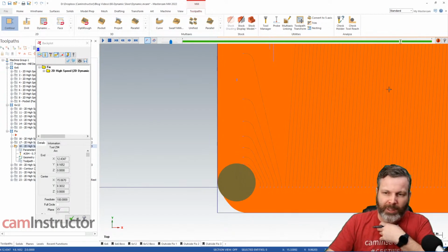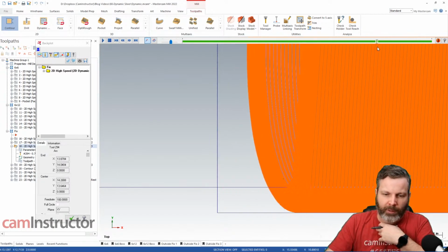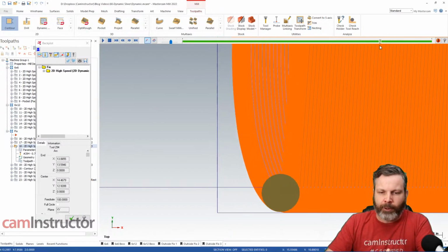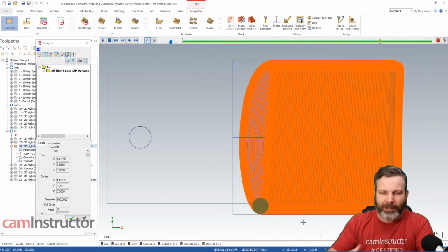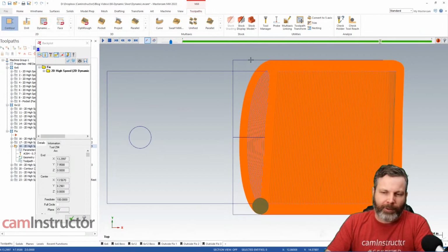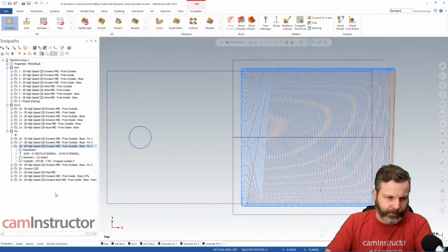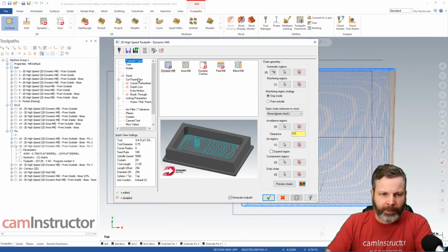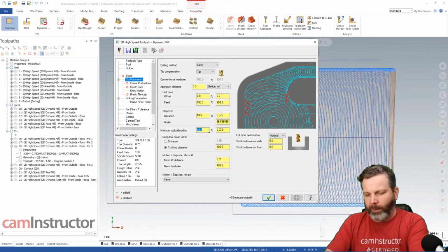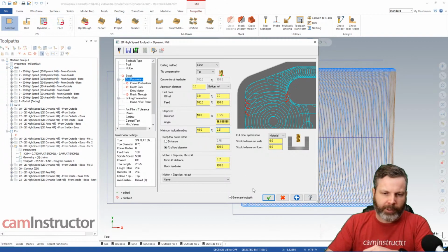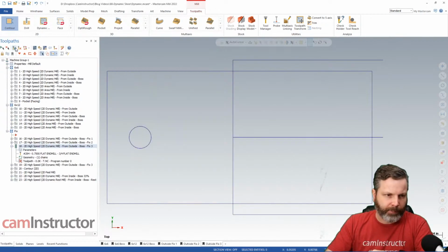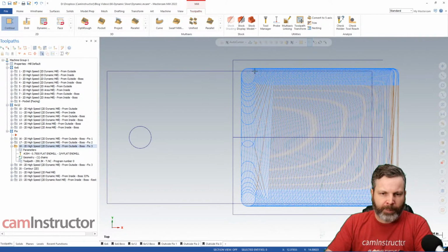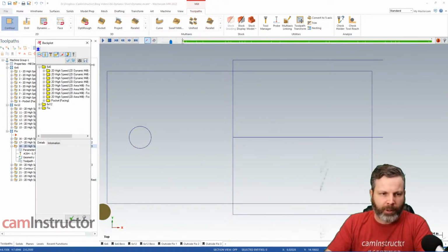And we don't need to be nibbling away at these corners. There's no need for a sharp corner if we're going to be machining all this stock away anyway. So what we could do here is fill the shape of the corner. We could limit the tool path here as well. We could say, I don't want to be getting down that sharp, so maybe 400. That'll keep it a little bit flatter, but even still, that's probably getting too sharp. It's too much work in the corners for a part like this.